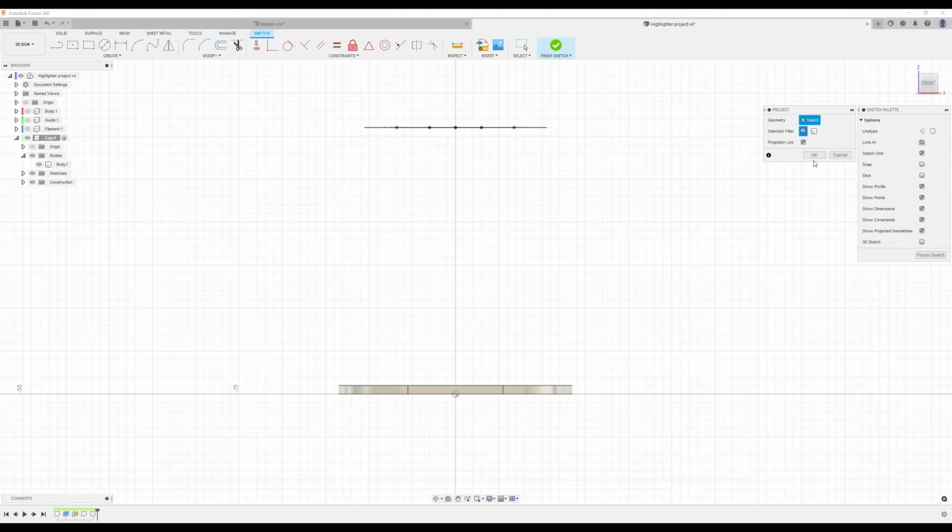I'm going to select 4 different lines. Make sure that specified entities is selected. Select this line, this line, this line, and this line. All right, click OK. All right, now we're going to use a 3-point arc. Select this point, connect to this point, and just bring a line out there. Let's go ahead and dimension it and make the angle about 220 degrees.